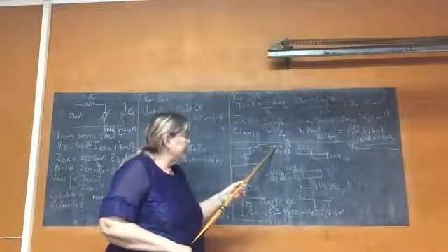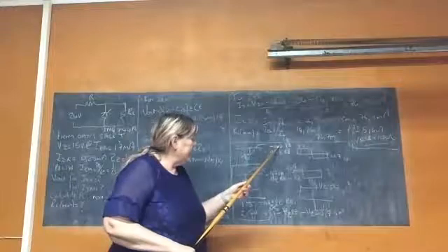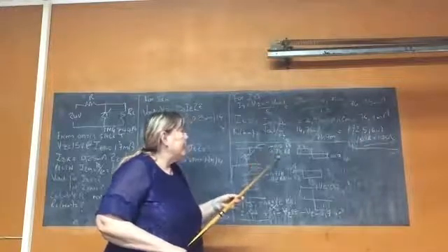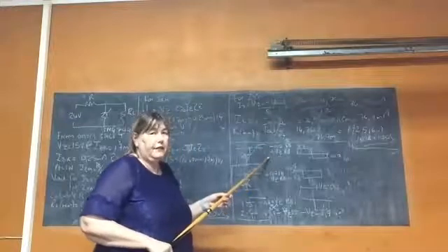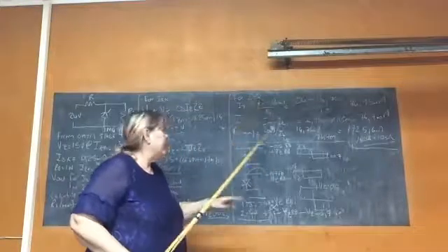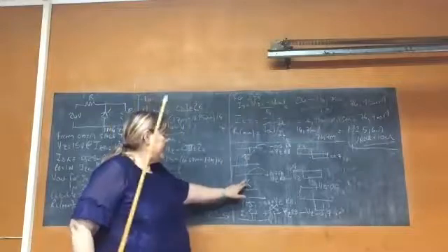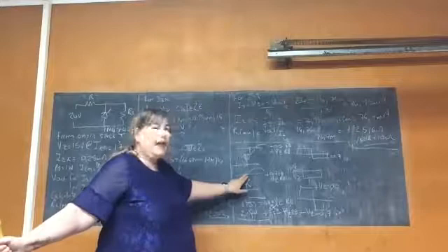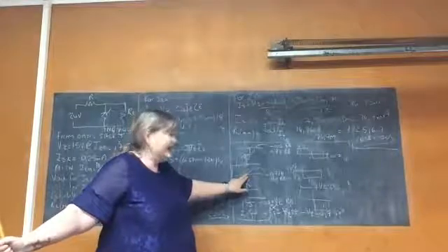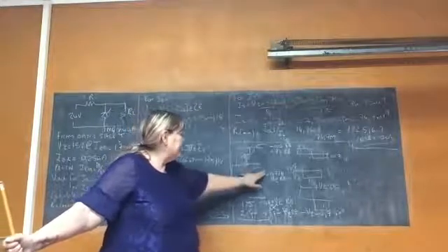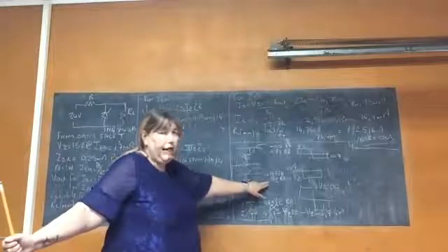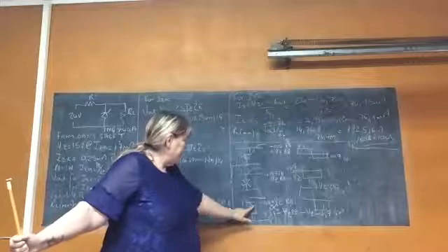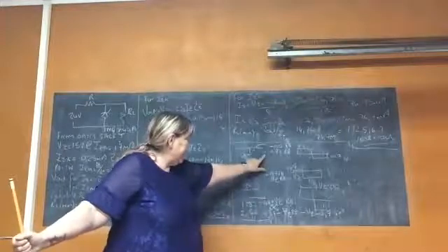And with the forward bias, it's minus 0.7. The reverse bias must be plus Vz. So, in this case, I have the anode here, so I will have a plus 0.7. And if I have a plus 0.7, I will have a minus Vz. Let's go back.